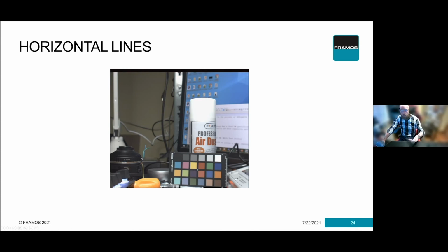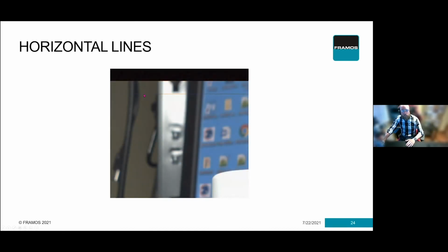The way that I simulated this was I enabled a test pattern where I could overwrite one particular line or multiple lines with a black line, and I did that. Now this line isn't black because we're looking through the Bayer pattern. If this was completely black along this pixel, it only means that, let's say, a green and blue line was taken out, and it will still take the average values from around it. So you can't say it would be black on the sensor. This is why we then look at the raw images.